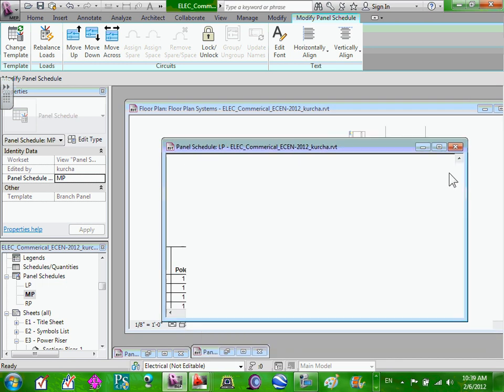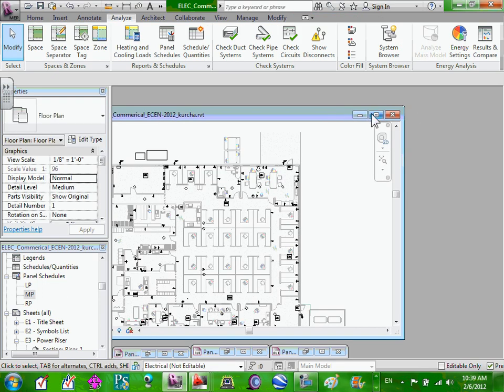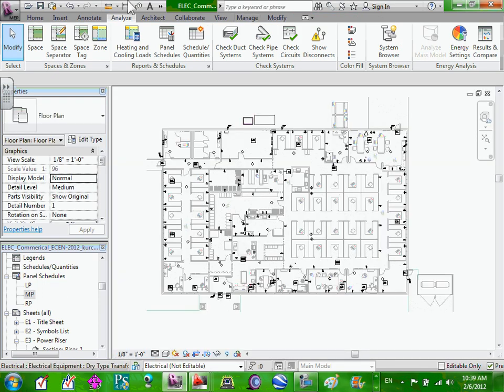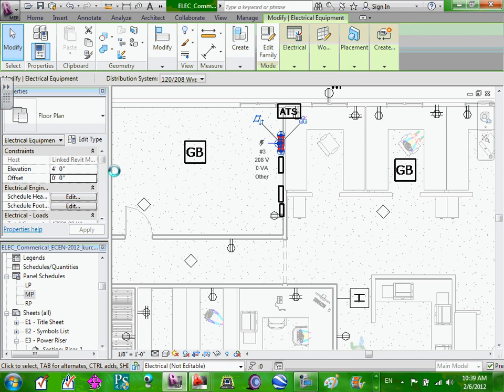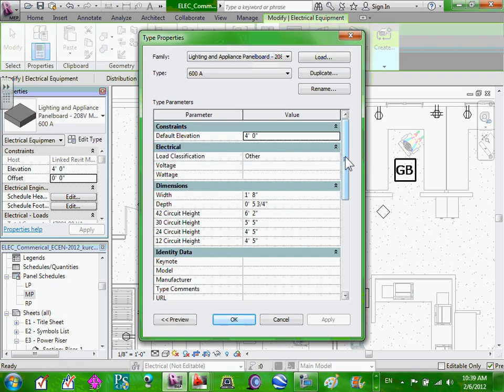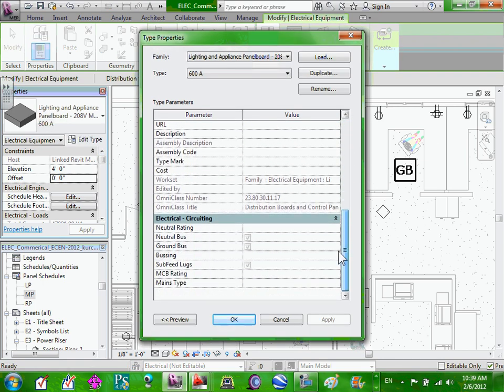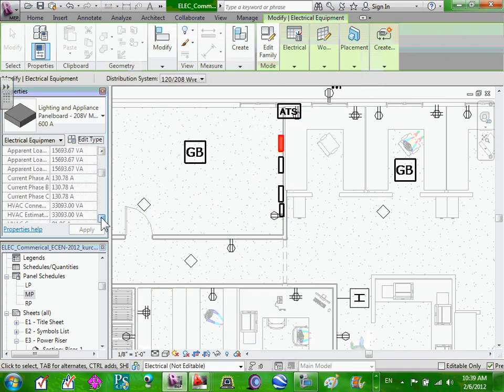Let me go see here what they said about these panels here. These gentlemen. Any question about running them, guys? You're going to be playing with these. The more you play with it, the more you get it. So I'm going to just see, here's my panel here. Don't know which panel that is. It's a 2.8 lighting panel. So if we name that panel and we tag that panel and we assign the amp, remember when we're assigning the amp, it will be pulling it, guys, from right here.